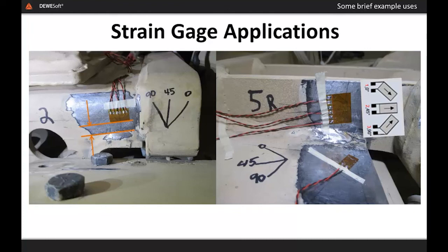We all know the weld is likely to be an early failure point, and placing gauges too close to them has a number of implications. One of which is that if a gauge is atop a crack, it won't see loads the same way, as the crack has already relieved the material of the loading effects. The other one is that welds cause changes in the materials that are typically very localized and can initiate microcracks due to the thermal contractions.